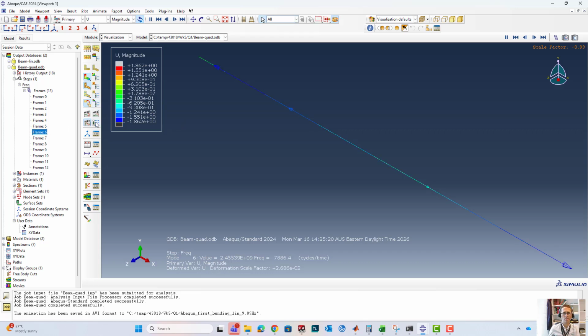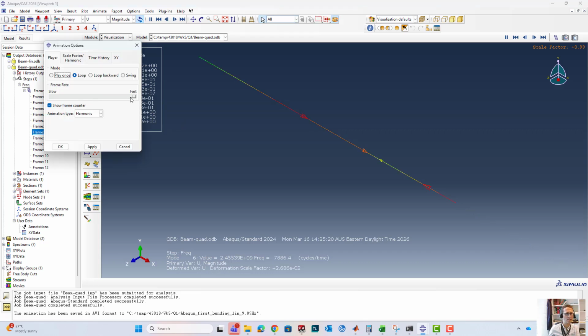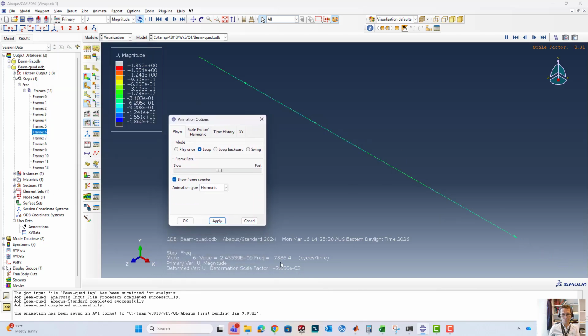If you look at the direction of deformation here, and if I actually probably slow it down, look how these are out of phase with respect to each other. So this mode is a 2 DOF mode where we're out of phase, in anti-phase, these two elements, and clearly it's a much higher frequency, 7.9 kilohertz versus 2.6 kilohertz, and so on.